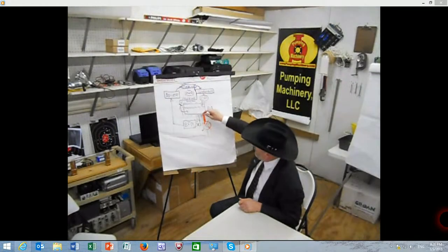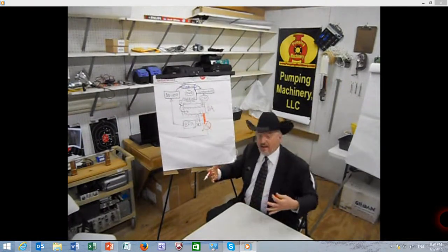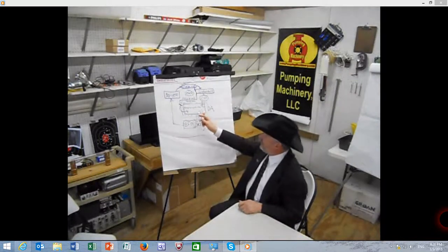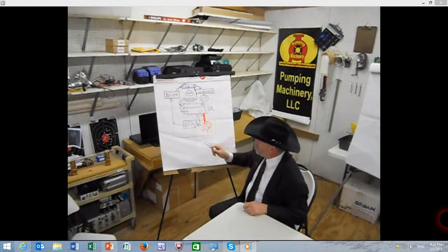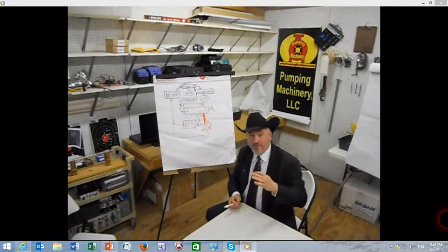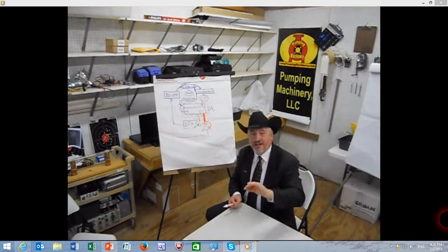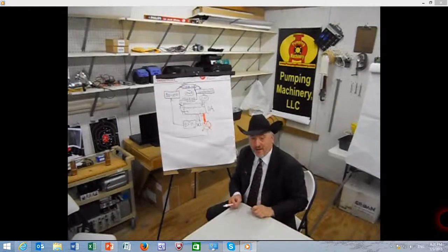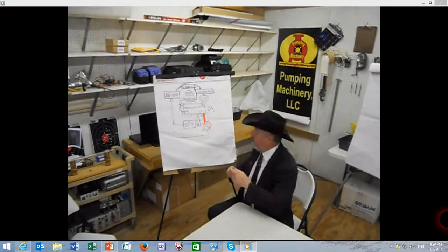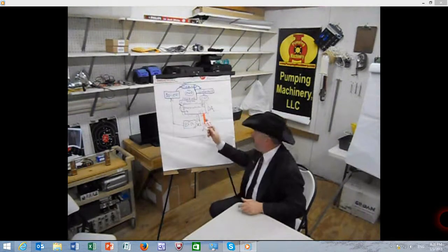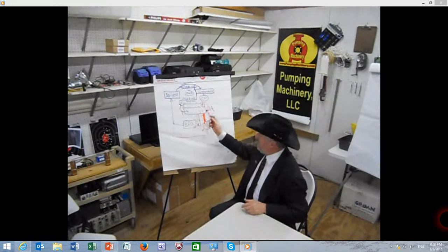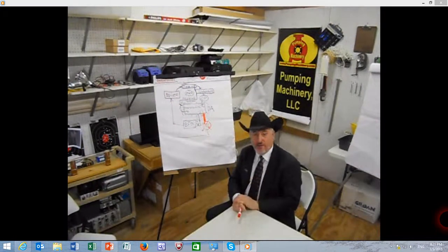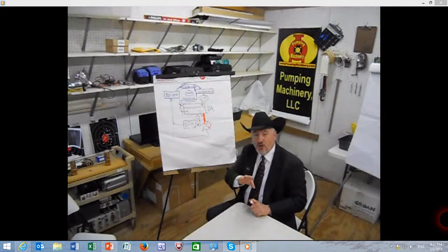As the vapor bubbles up, expanding, it can now encounter a lower temperature zone in the DA and in the suction head of the second pump. When the vapor gets to a colder region, it is transforming back into the liquid. It takes a fraction of a second, milliseconds. The question now remains, what will happen with the flashing of this pipe? Will this pipe, the first pipe, affect what happens in the second pipe and therefore affect the boiler pump or not? So we're now going to look at two scenarios.